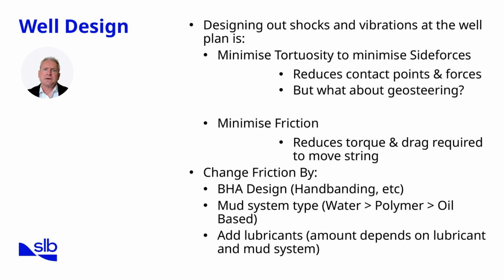Another important factor is friction. Reducing torque and drag improves the drill string's ability to move smoothly through the well. Friction is influenced by bottom hole assembly design. For example, hard banding can reduce wear at contact points. The mud system also matters. Water-based muds generally provide higher friction, while polymer and oil-based systems reduce it.